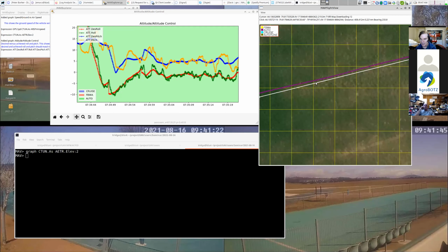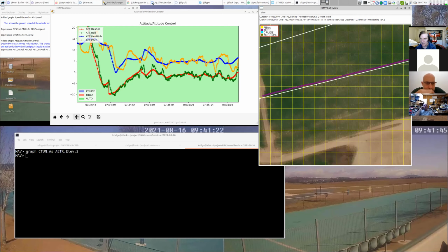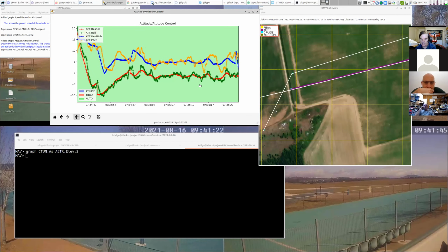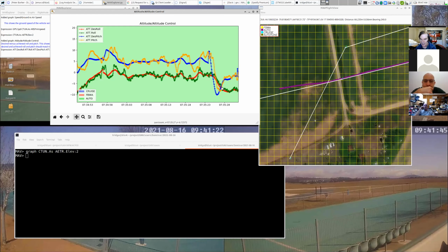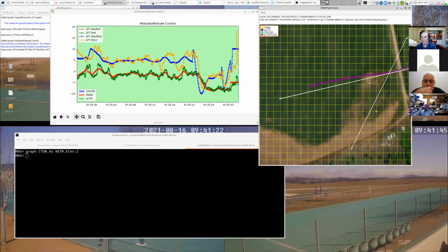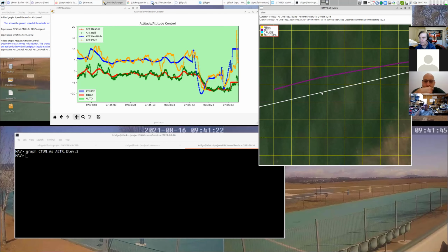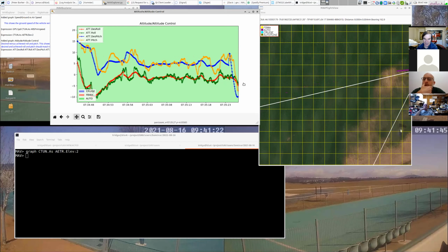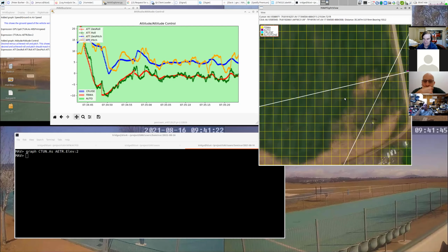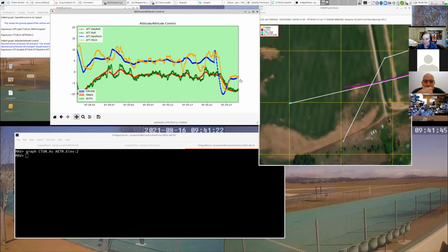If we have a look at the distance that is off, he's off there by about 1.2 meters, which is not bad for a little foamy. And so he's coming along there, and then he starts diverging. So there's where it's getting interesting. About here, there's a couple of things that happen. He's coming up to this landing point, and you can see that he was tracking really well up to this waypoint, and now he's off by 8 meters, and it's just getting worse. We also notice in the roll and pitch that he is flying fairly level up to this point, and then he suddenly is not flying level, just after he enters this final waypoint.